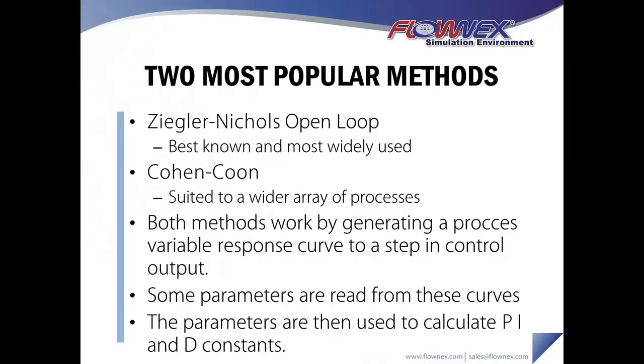Both of these methods work by generating a response curve from a step input in your control output. Some parameters are read from these curves and then used in calculations to determine the P, I and D constants.